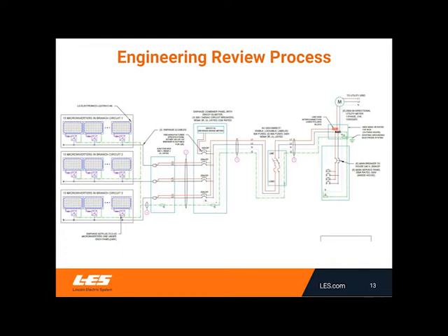So we need to have some kind of protection of the system beyond that. This one shows a tap box with some connectors. You see the house panel there on the right, and the photovoltaic system is connected through a fused disconnect switch. When we look at it in one line like this, we say, okay, you've got some fusing there, that meets our requirement. You've got a disconnect there, that meets our requirement. And then the other documentation will show the location of those devices.